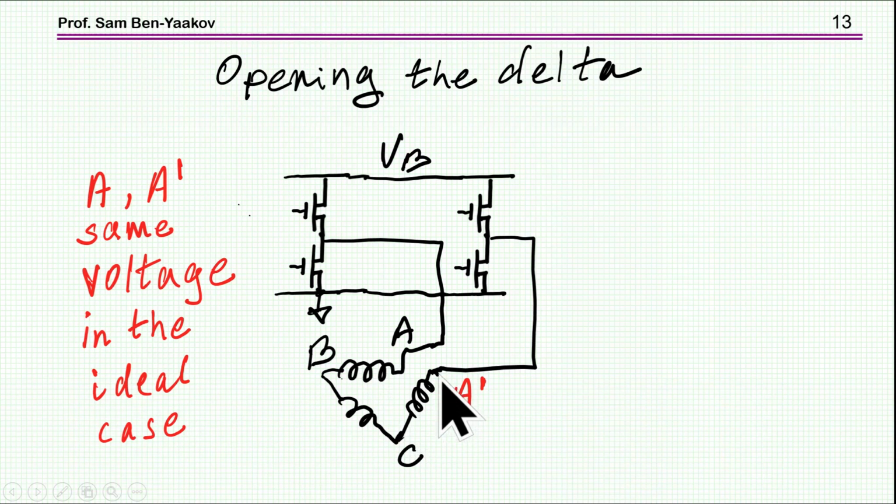By separating them and filling each one with a half bridge, I can actually control the value here. So I have another degree of freedom here to adjust the voltages. They might be a little bit different, such that I can control the currents in the coils independently.